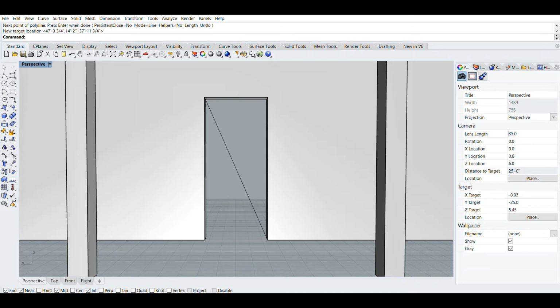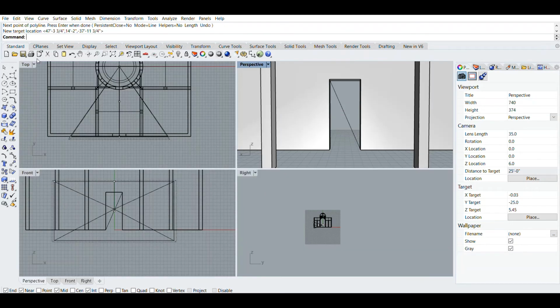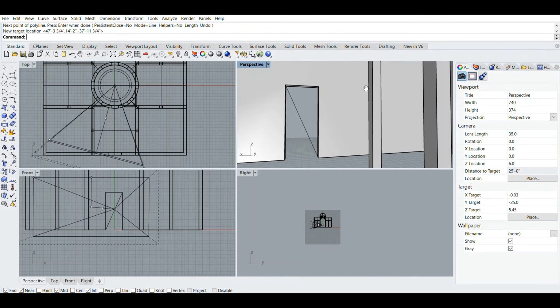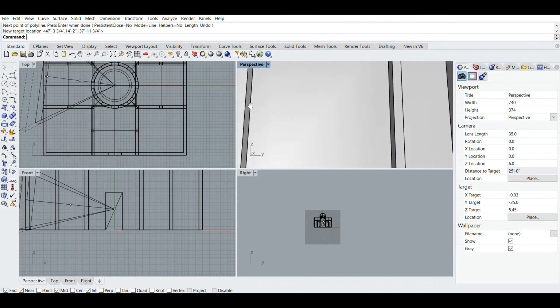Okay. Once we're here, if I move around, I'm going to basically move the location of my camera. In order to look around but not change the location of the camera, I can hold down Control Alt and right click in my mouse and just look around.